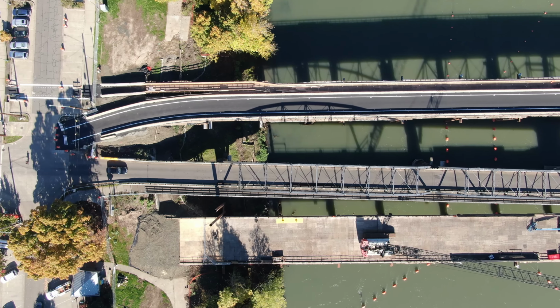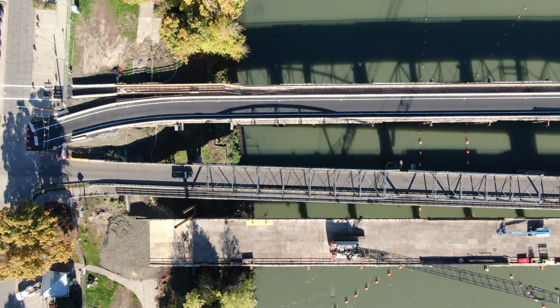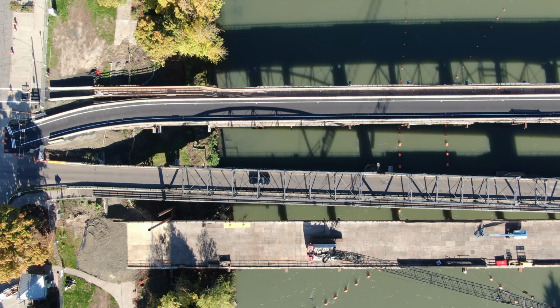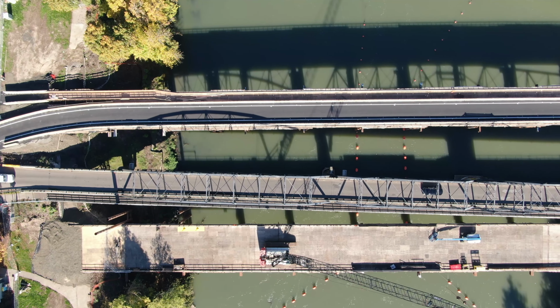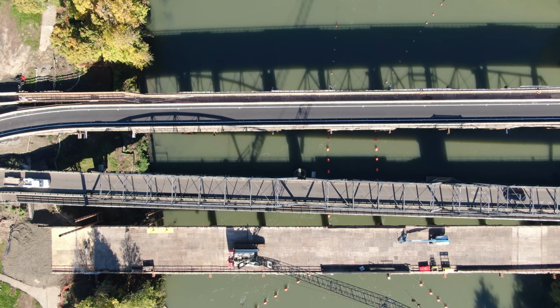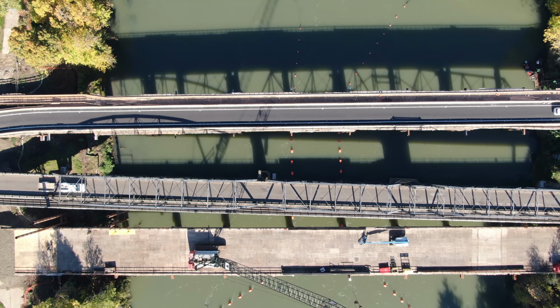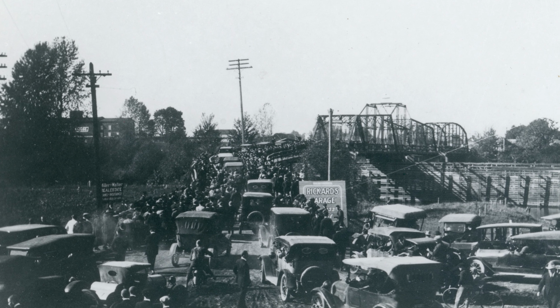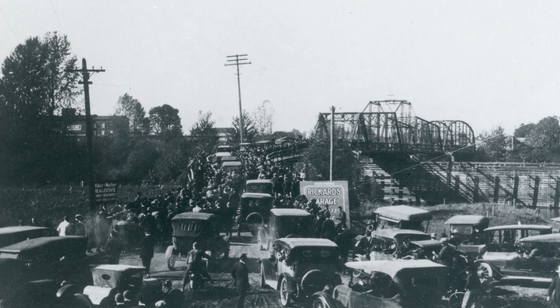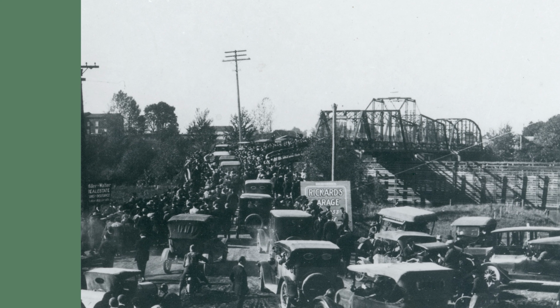The most common loads on a bridge are dead load and live load. Dead load is just the bridge having to carry its own weight, and that's the biggest job a bridge is going to have. Live load is the vehicles that are on it. Typically we consider trucks on the bridge, although pedestrian loading can be significant. If there's a bridge that's closed and there's a major event where thousands of people are on it, it can see more loading during those times than it would with trucks.